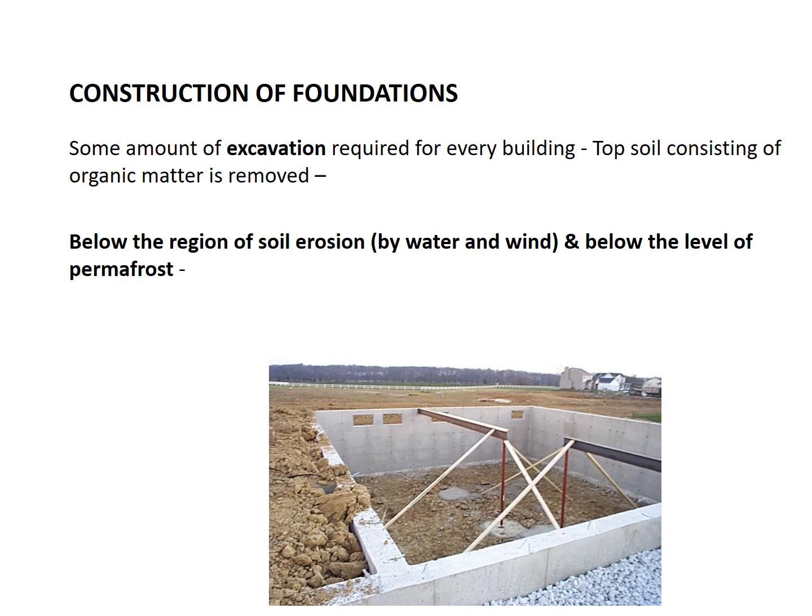So about the construction of footings, some amount of excavation is required for every building. Topsoil consisting of organic matter is removed, and then excavation goes below the region of soil erosion, that is, by water and wind, and below the level of permafrost, to the required depth at which the bearing capacity necessary for the building is met. That's how the depth of an excavation is decided, by all those factors. And a variety of machines are obviously used for excavation.